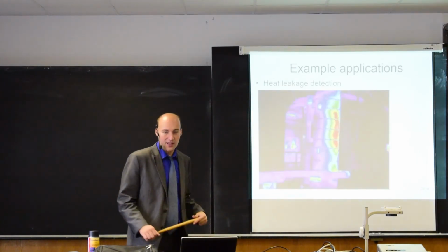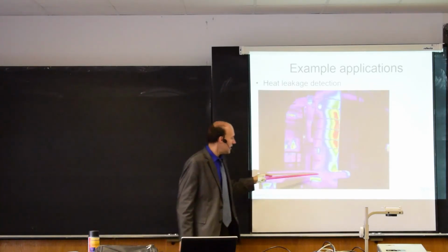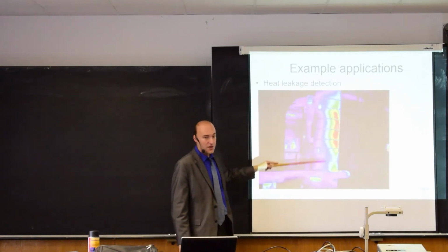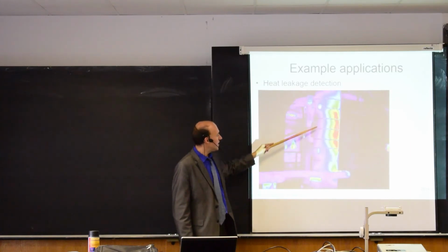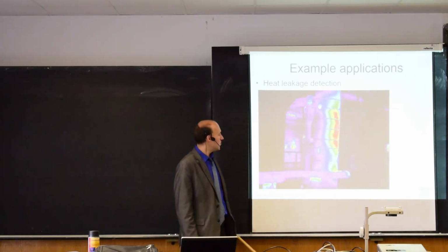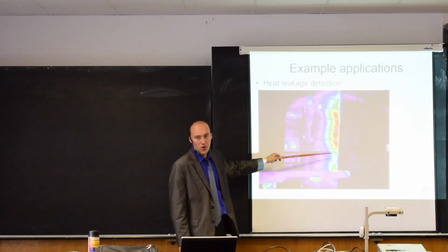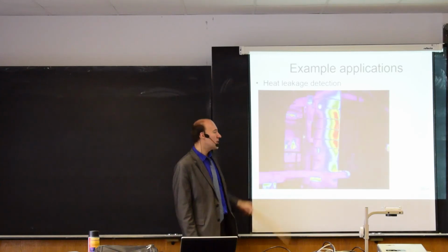We can detect leakage under some insulation. So here you see there's a pipe, and if there is some leakage under the insulation, then we can see, okay, here it's a little bit warmer, and this can be detected.